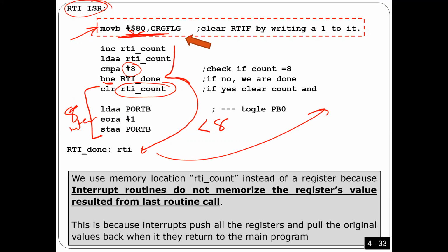Okay. Very simple. That's what the coming lab is, the easiest lab. In the coming lab, guys, because I know it is the end of the semester, you don't have much time, but it's a very easy lab. What I'm saying is that if I want to modify this program to flash the LED every 2 seconds, very easy. I'm going to make this one 16. That means I'm going to execute this part every 16 interrupts, and 16 interrupts means 2 seconds, because you multiply 16 times 131 milliseconds. It means 2 seconds. Is that okay?